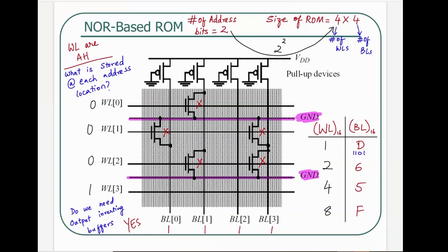All right, there is one more question that I want to answer here, which is, is this one-dimensional decoding or is this two-dimensional decoding? 1D or 2D? One-dimensional decoding is absolutely correct. We are only doing row decoding here. If we did two-dimensional, then we would only be reading 1 bit. We are right now able to read 2 bits. So we are only doing row decoding in this case. All right, questions about this?